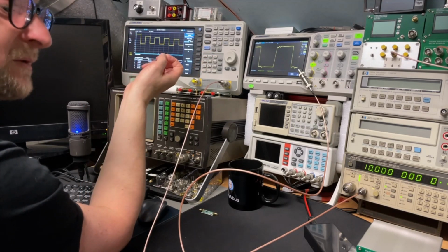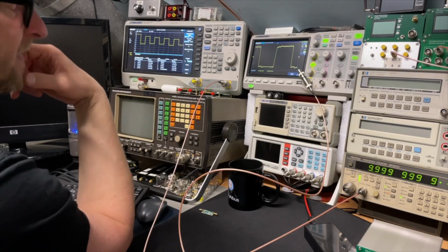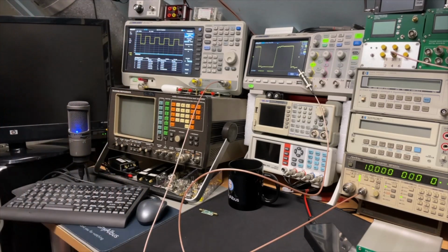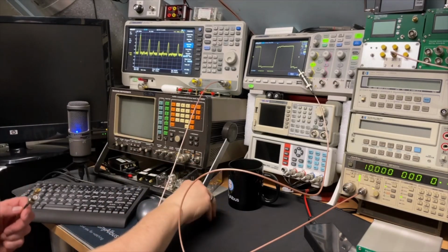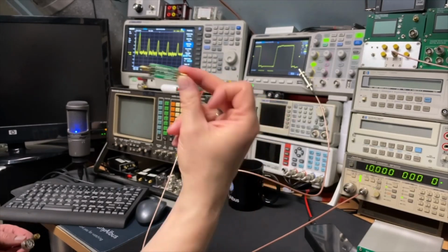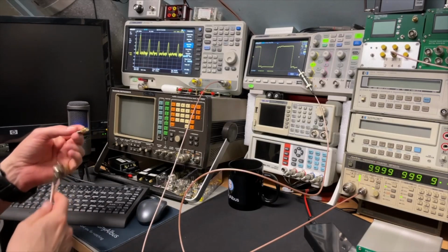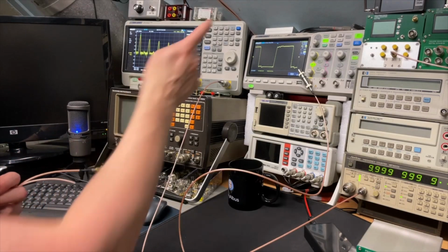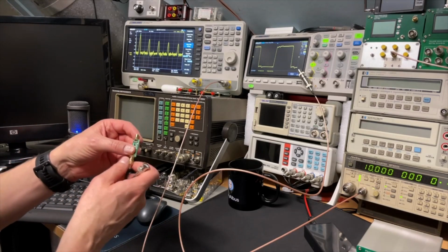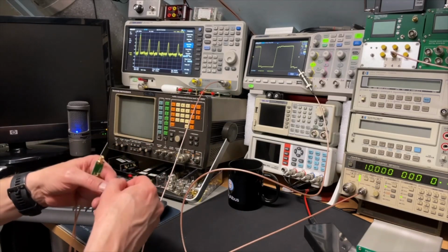But you can get maybe a little distortion. And if you have really good equipment, maybe it even has a band pass filter to only look at the 10. And I will show you how the band pass looks like. So what you can do is have these little band pass filters. This filter only allows 10 megahertz. So everything below and everything above will be filtered out. And that also will make it look different on the oscilloscope. So let me get this band pass filter here. I need 2 BNCs.